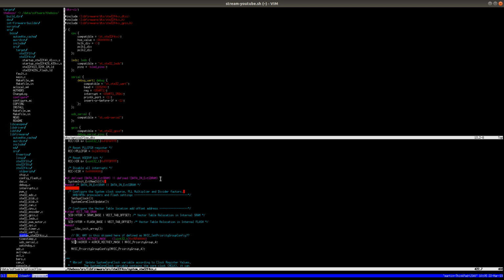Right, so this code just initializes the NVIC. So when we now modify the clocks, if I move this code to a device driver, then FreeRTOS will initialize using the 16 megahertz RC oscillator. So it could actually be that we get the LED blinking much slower because, let's see, bare or FreeRTOS. Well, this is a bare executable, but it uses FreeRTOS for threading, for the scheduler, basically.